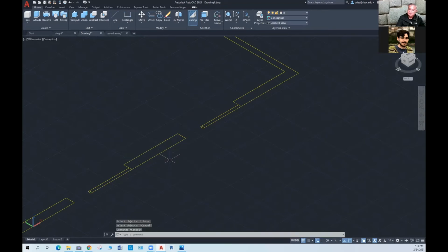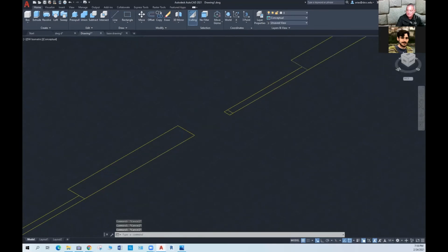Now, because you have this object as copy and paste, and that's one of the reasons I do that, I could make these objects polylines, right? So I could do PE, select it, make it a polyline, and then join 1, 2, and 3. I'm not going to join that last line because actually I need to break it first. But I just created a polyline there.